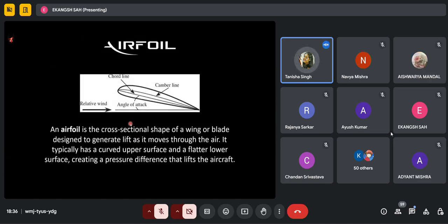So an airfoil with lift also has an angle of attack, as shown in the figure. The relative wind is the direction of wind at some distance from the wing. It is parallel to and opposite to the direction of motion of the wing. The velocity of relative wind is equal to the speed of the wing. In aeronautics, the geometric angle of attack is defined as the angle between the mean chord of the airfoil and the direction of the relative wind.